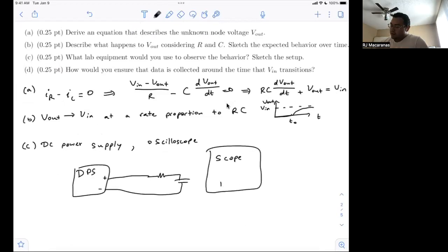And on channel 1, we're going to connect maybe to this input. So there's the plus end of our probe. There's the minus end of our probe, the ground end. And then on this second channel, we're going to observe the voltage across this capacitor here.